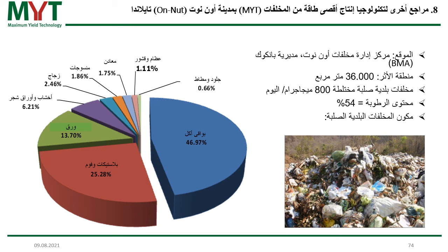It's within the Bangkok Municipality Administration at one transfer center in Bangkok. Bangkok has 3 transfer stations. It's quite small, only 3.6 hectares. It's processing 800 tons per day. And here the moisture content of the MSW is 54%. When you look at the characteristics, it looks quite different to what we receive here at Ringsheim. It has nearly 50% organics, then 25% plastics, 13% paper, wood, and a small portion of glass, textiles, metals, bones, and shells.